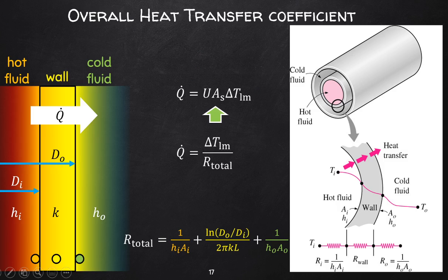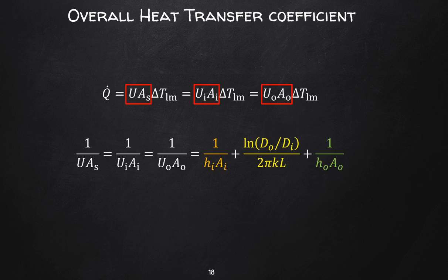Now the summation of these yield what is referred to as the overall heat transfer coefficient, and is specific to the current application and equipment in question, but the overall heat transfer coefficient is also defined per fluid. It can be defined for the entire system, but in fact there should be more than one coefficient per transfer area, taking into account things like fouling, etc.